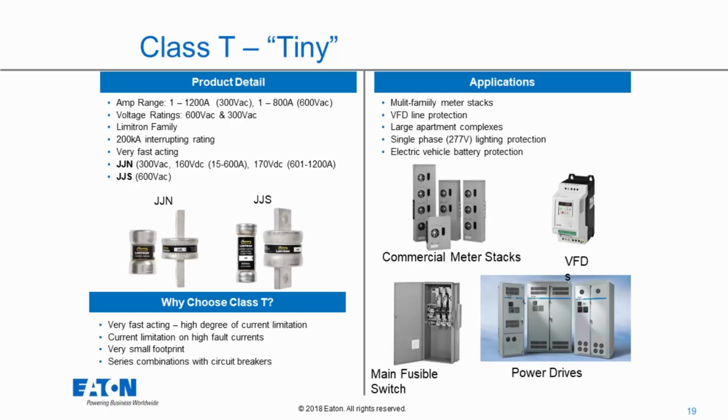So we look at applications for these things. We've got multi-family meter stacks. That's a very popular application. We've got VFD line protection. So if there's any engineers on here or anybody does industrial control, many times you'll see it on a spec for variable frequency drives that they'll say, you know what, we need to use a Class T in front of this drive to make sure that we protect the system.